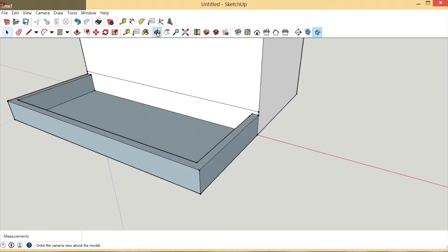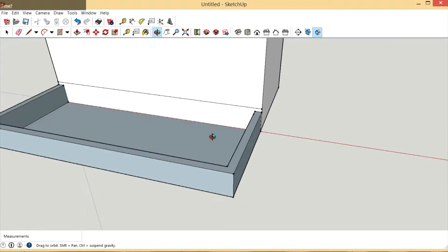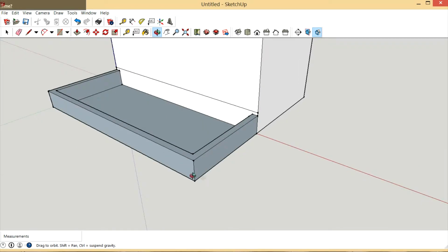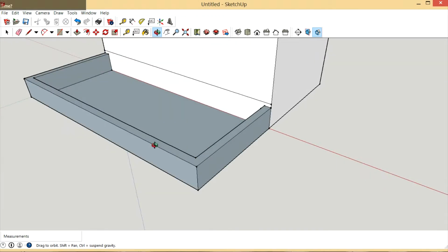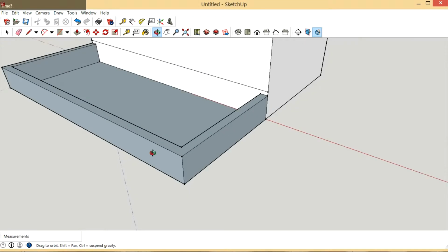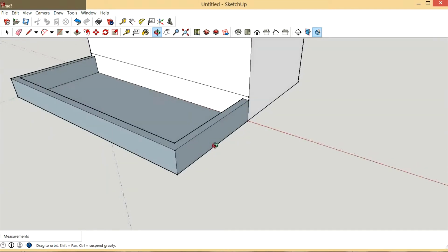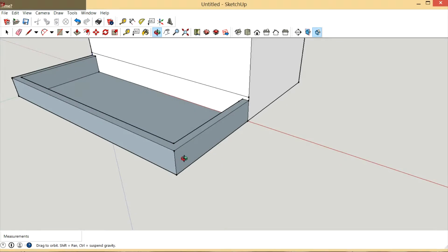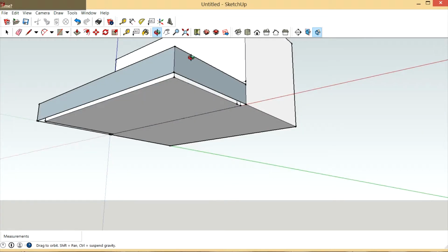And for a footing, if you have good hard ground like we have in Tennessee, where we have this chert, it's basically a clayish soil with lots of rock in it. We complain about it, but it's great for building. We would typically, I tend to overkill a little bit, use a 24-inch wide foundation, and you can get by with about 8 inches deep, but I like to make it a foot deep because that's just how we roll.